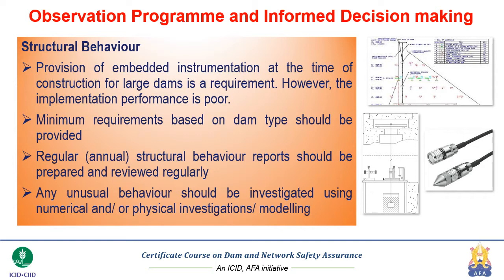But still, there are minimum requirements that are based on the dam type. In case of the concrete or masonry dams, the deformation or the deflection of the dam and the uplift in the dam, as well as the pore pressures in the dam and the quantum of seepage through the dam, are the absolute minimum requirements which have to be implemented, so that we have at least some idea about the status of the dam.